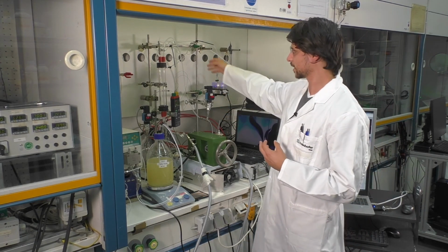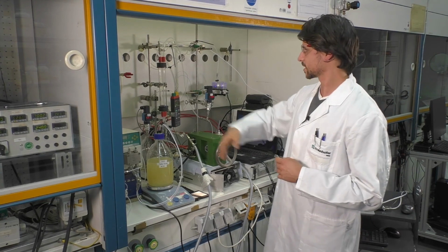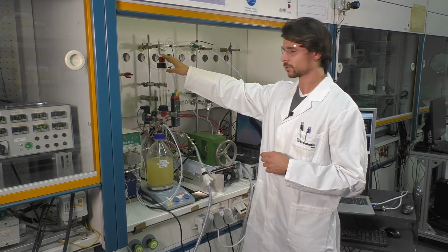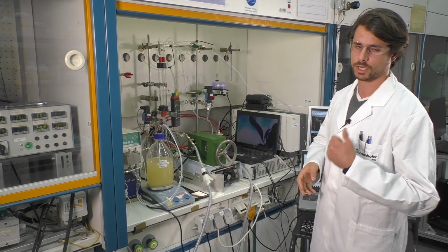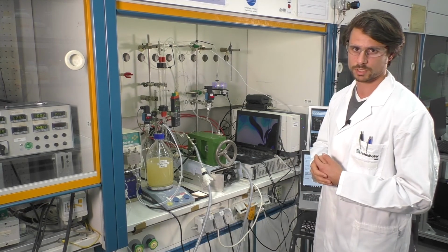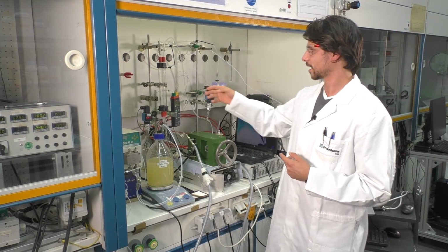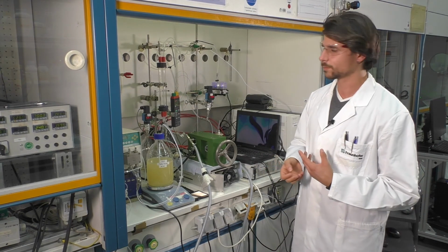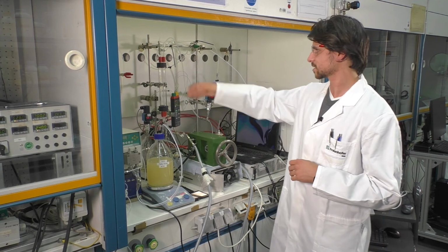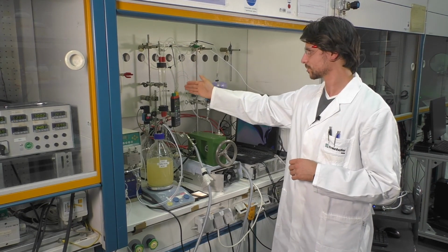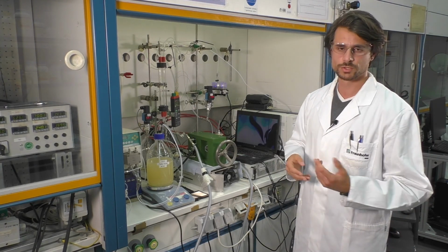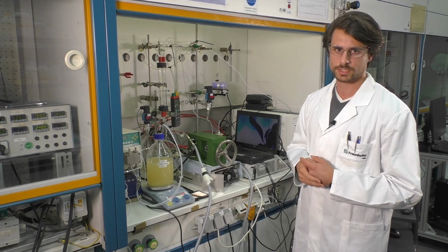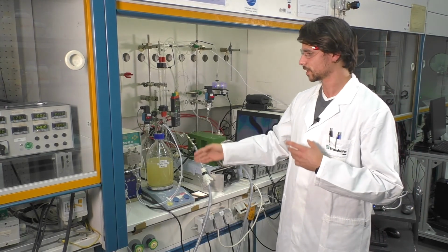The product is then collected in this tube or column here, where there's a lot of foaming. We also have a process micro-GC, a 4-channel micro-GC, which can detect the gases, which are carbon dioxide and hydrogen, and some gaseous hydrocarbon byproducts. After we wait some time, we will see that the phases separate: the gaseous phase, the hydrocarbon phase, and at the bottom the aqueous phase, which we can then reuse again. Depending on the converted quantities, we can add some fatty acids and realize a continuous process. Okay, so we start the reaction now.